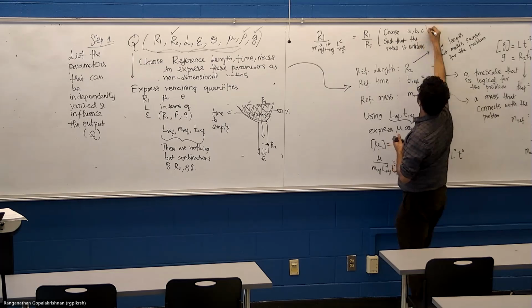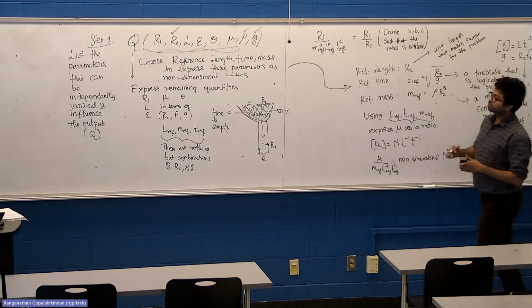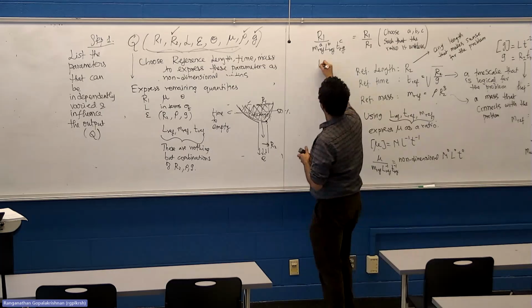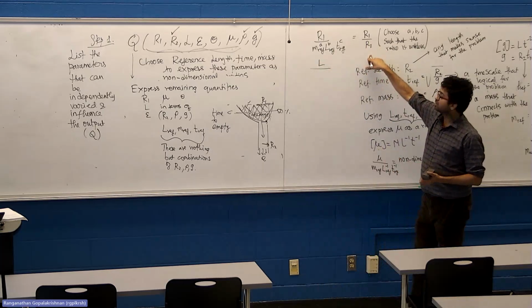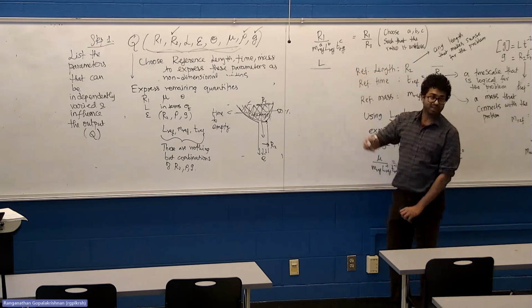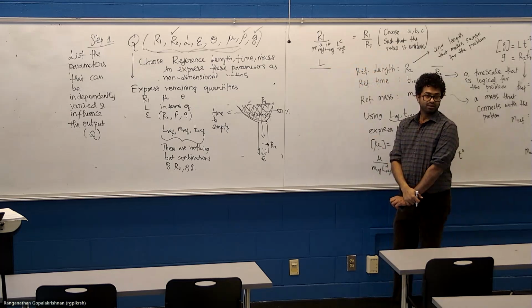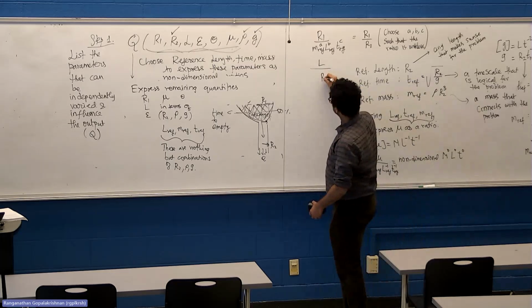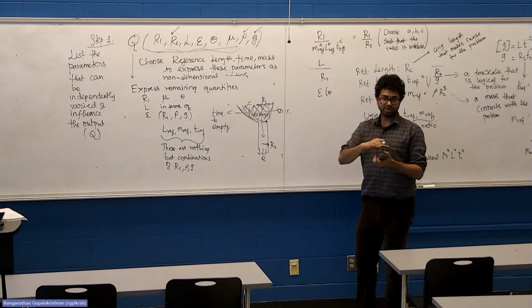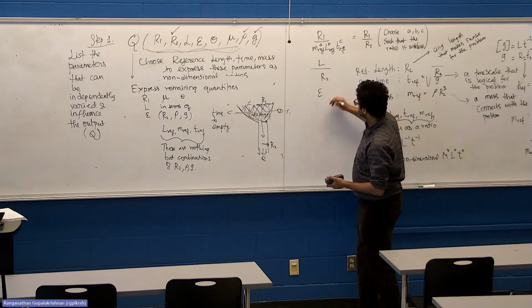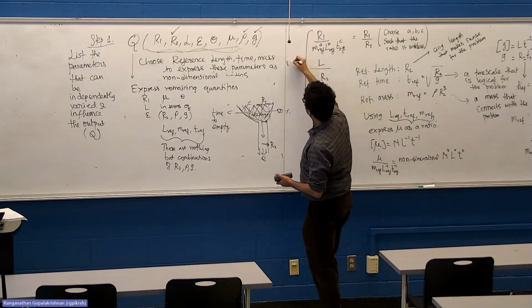How to express, let's say, L in terms of the three quantities? What's the natural choice? If I want to non-dimensionalize L, L over R2. If I want to non-dimensionalize epsilon, which is a roughness, like if you measure the roughness in millimeters, it's also a length. So epsilon over R2. So these three all are ratios that are dimensionless.